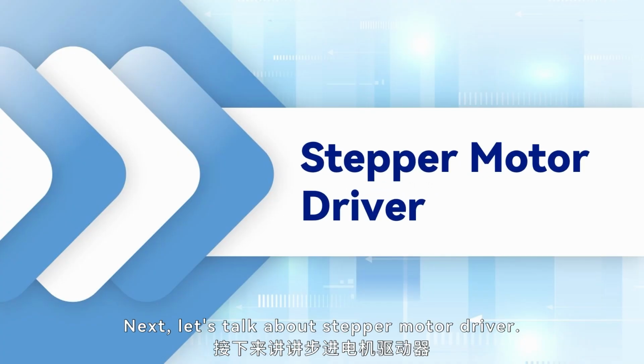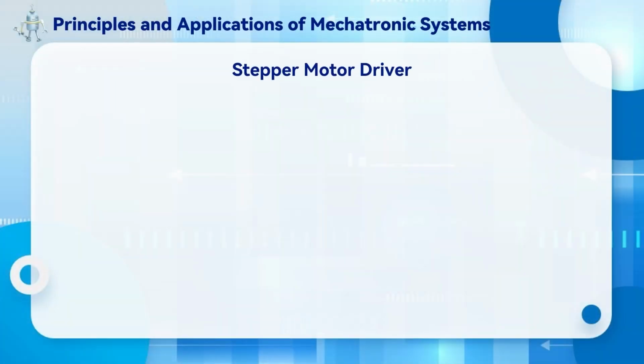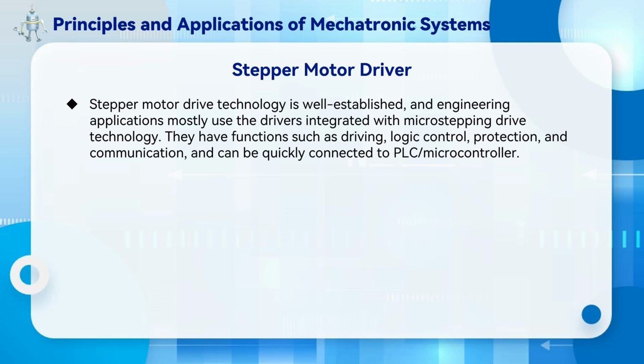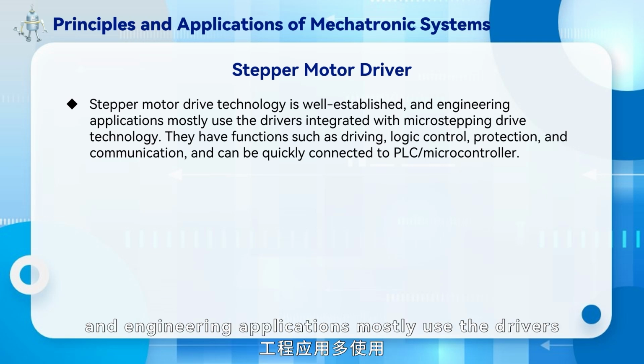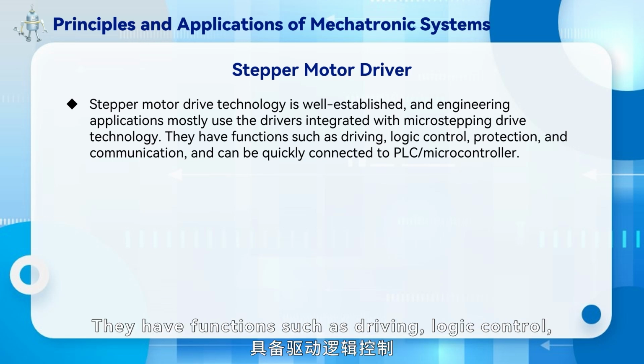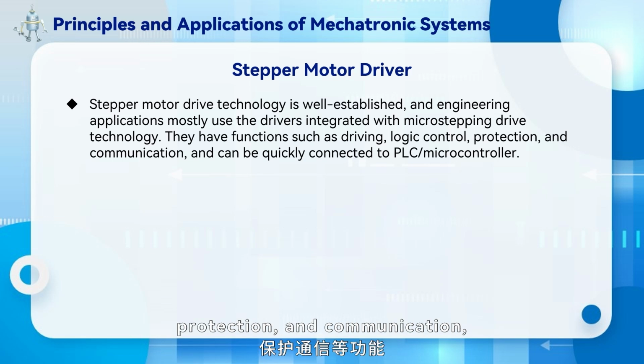Next, let's talk about stepper motor driver. Stepper motor drive technology is well established, and engineering applications mostly use the drivers integrated with micro-stepping drive technology. They have functions such as driving, logic control, protection, and communication.